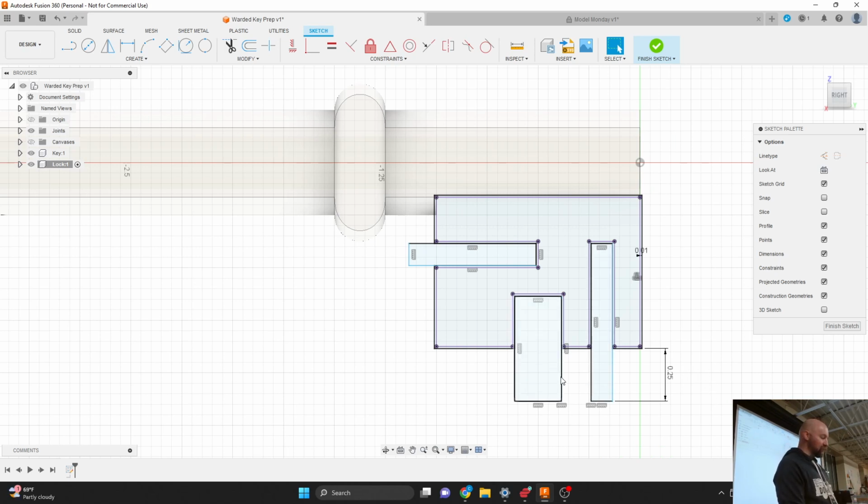And if I were to specify dimensions twice here, if I were to do this 2 times, I'd have to change both of those dimensions, whereas now I just have to change the one, and the other just follows along. So it just kind of stays coincident. Using rules to define the distance can be really handy, for sure.